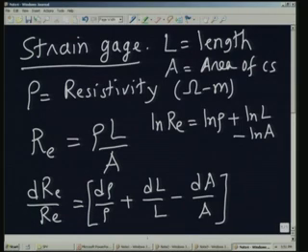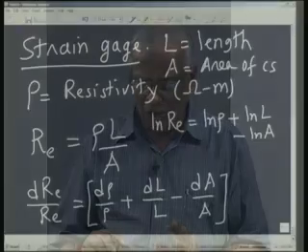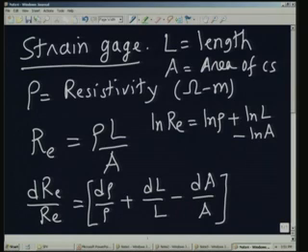So, what I am going to do actually in the measurement using the strain gauge as a transducer for measurement of strain is to note the change in the resistance with respect to the original resistance. It is just like strain, change in length divided by original length is the strain, mechanically we call it the strain. In the case of resistance, it is the change in the resistance divided by the original resistance. So, on the right hand side, the changes in these quantities lead to a change in the resistance. This is the basic theoretical framework on which the strain gauge is going to work.